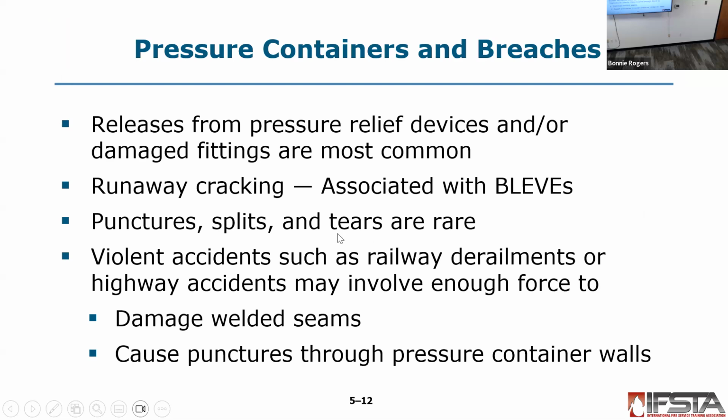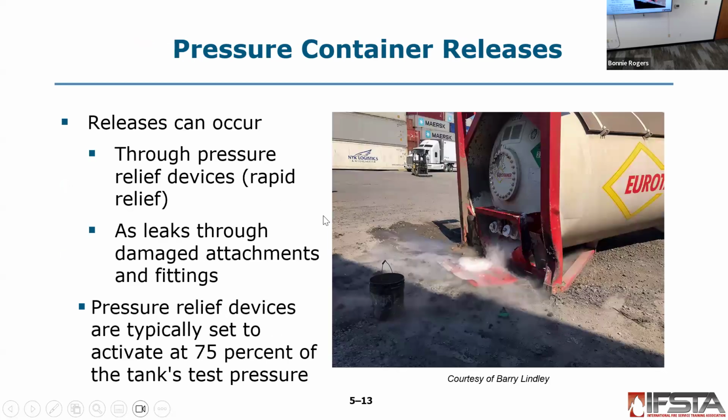Flooding. Punctures, splits, tears are not as common, but we could have accidents, especially during transport. So pressure container releases can happen through the rapid relief valve or damaged attachments and fittings. Typically, they'll activate at 75% of the test pressure.